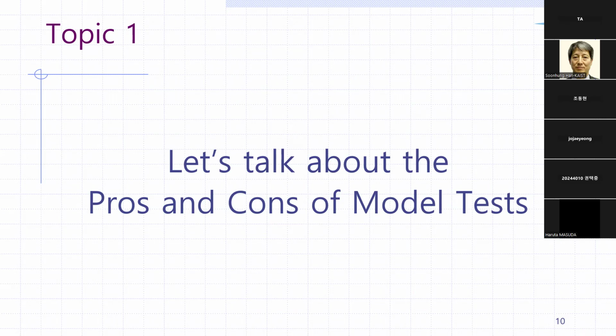What I got in mind is that there are two non-dimensional variables. They don't... but we cannot match the two numbers in one model. Yes, that is also correct. That's one of the things that I said. So based on Froude's hypothesis, to calculate the frictional force, the Reynolds number cannot actually be used. So we use an empirical function, but ITTC has come up with other methods to estimate the total resistance of real ships more accurately. So yes, that is also one thing.